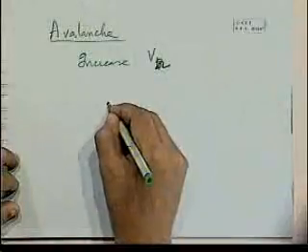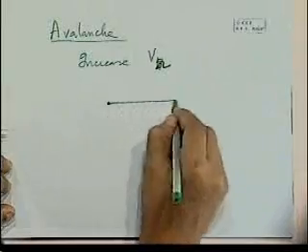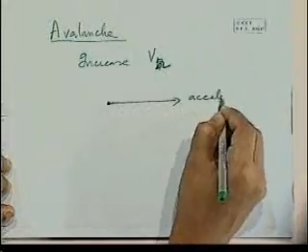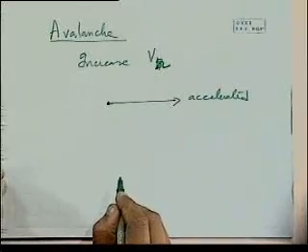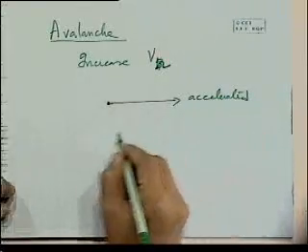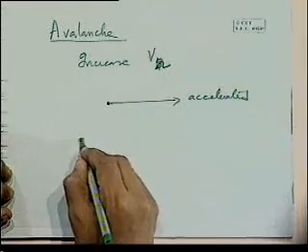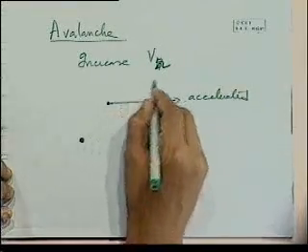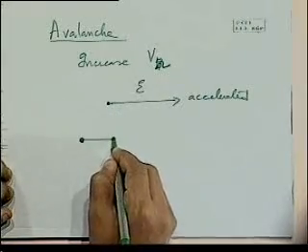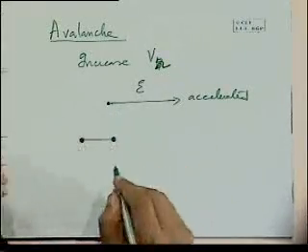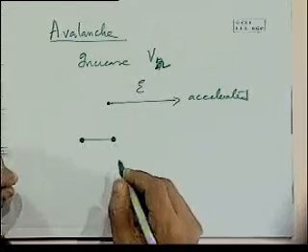So now the electrons are going to be accelerated much faster. They pick up energy in transiting through the diode. And this acceleration ends up such that they will have enough energy with the increased field to go and knock another electron out from its position, basically to start breaking bonds.